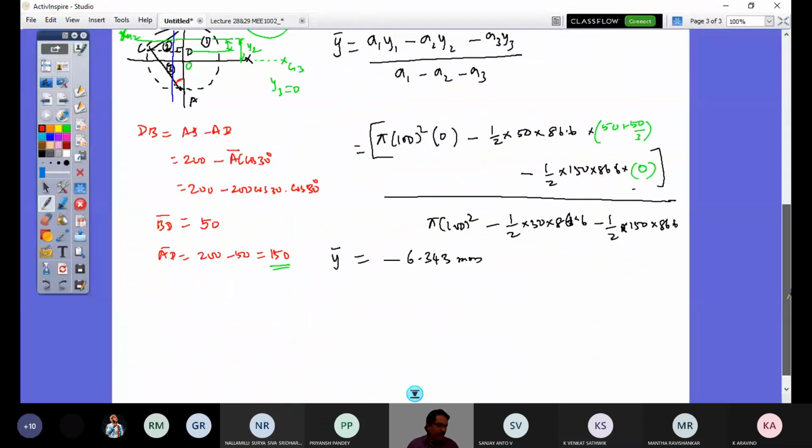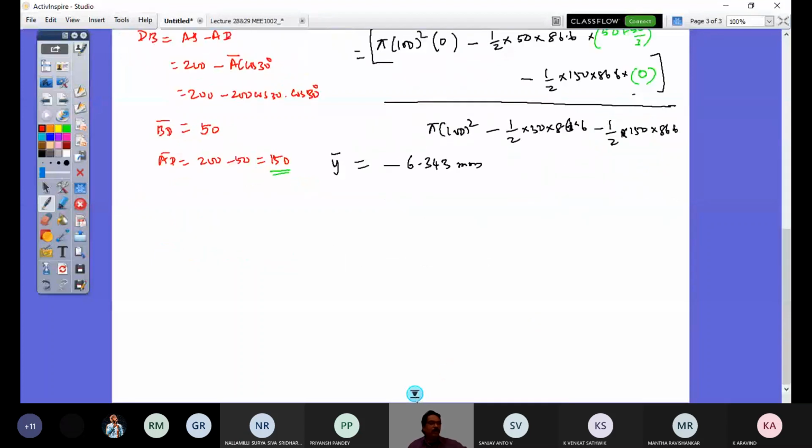So now for the second part of our question, we are able to locate the horizontal and vertical central axes of the given composite section, the shaded area. And now I'm going to calculate the second moment of area about that section. How do I do so? We have the parallel axis theorem to help. So let me write down the formula of Ixg, the new axis that we have found for the composite area.